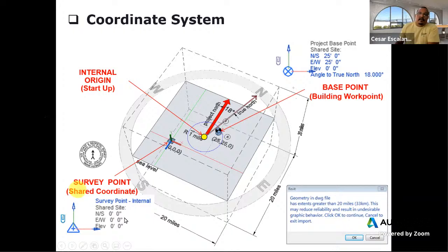And so inside of the project, by default, when you start a new project, both project north and true north are aligned in the same direction. They are pointing up on the screen. And you know the difference between project north and true north. Project north is the orientation we give to our floor plates so that they appear orthogonal in our sheets, and it allows us to represent our buildings in an orthogonal manner.